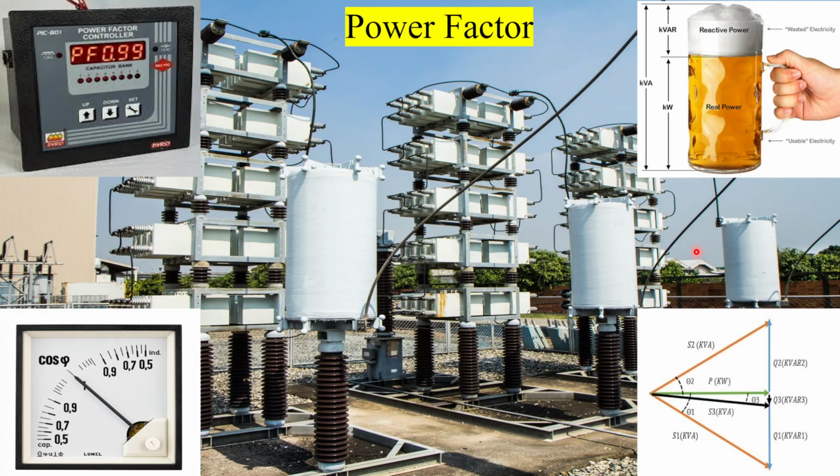There are two common causes of low power factor: inductive load. Many electrical devices, such as motors and transformers, are inductive in nature. These devices create a phase difference between voltage and current, leading to the generation of reactive power. This phase difference causes the power factor to be less than 1.